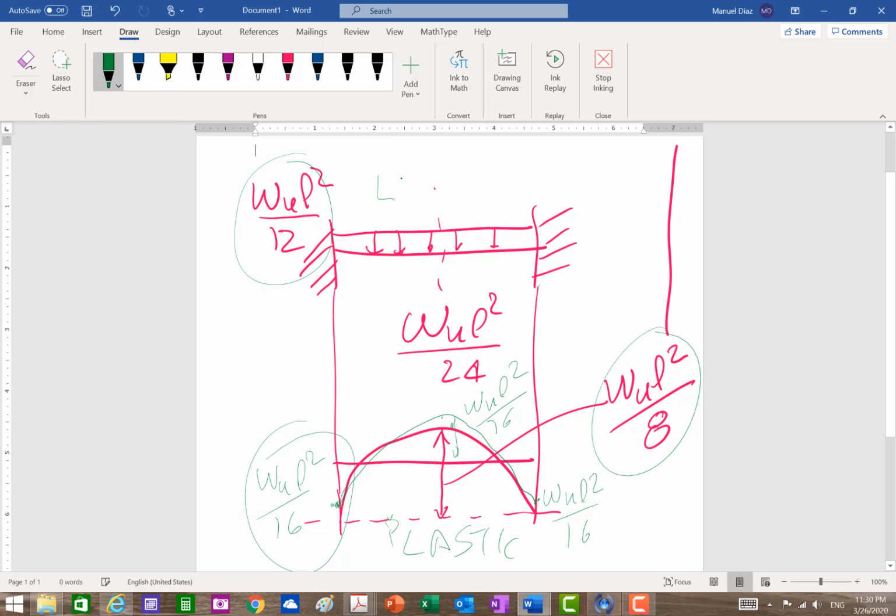And this one is linear elastic. So depending on the type of method that you're using, you will get different answers, right? But for this case, you have to design this to have that plasticity. It has plasticity meaning that it flows, right? That yielding there. So that's very important. Otherwise, it will not work.